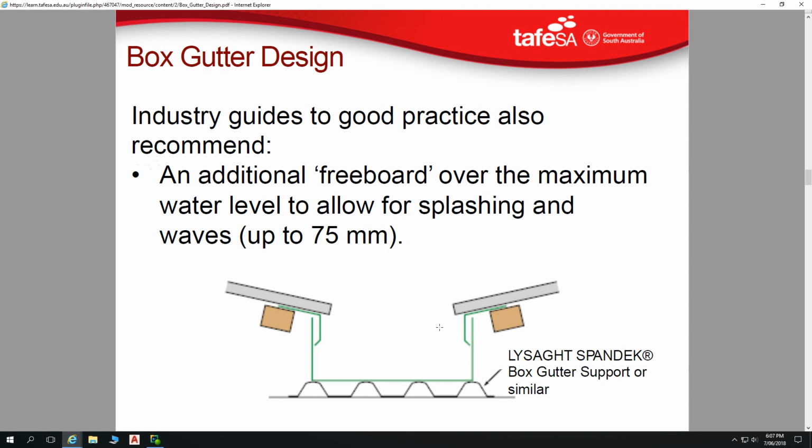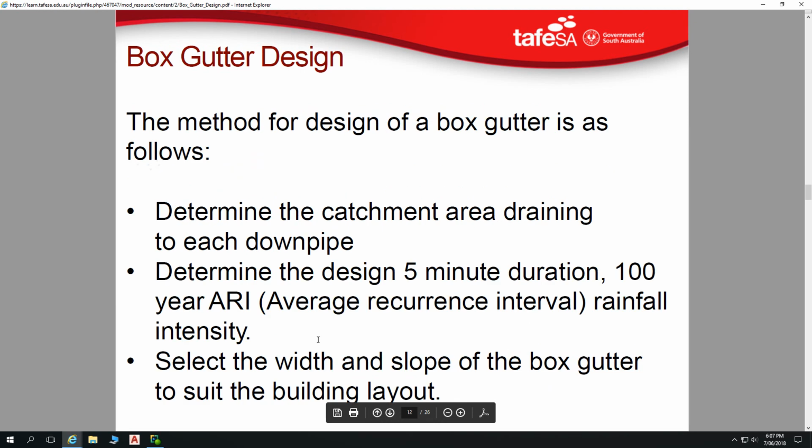But the whole thing of freeboard, that just means additional height. The term freeboard comes from boating. So a boat that's in the water, I've got our waves here like this, our boat in the water. That area that sits up above the water is the freeboard. So it simply relates to that. It's an extra bit there beyond your wall height.